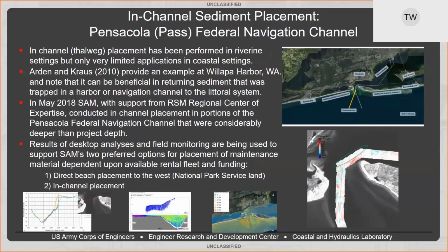First they analyzed to predict where the sediment would go, and then they placed sediment in the deeper spots of the channel and the inlet. Right now they're monitoring the project to ensure that the sediment is going out the inlet and back into the littoral process.